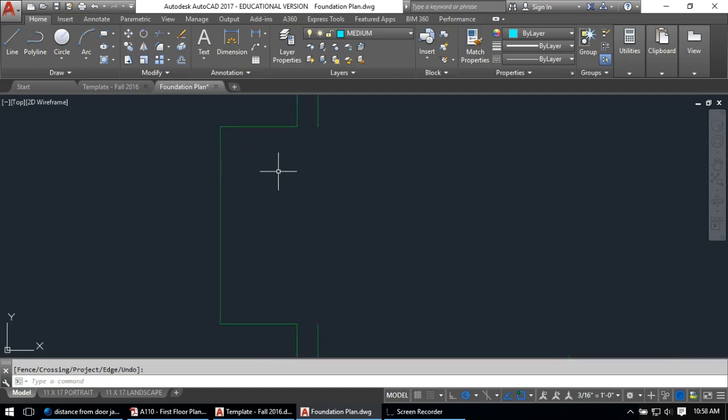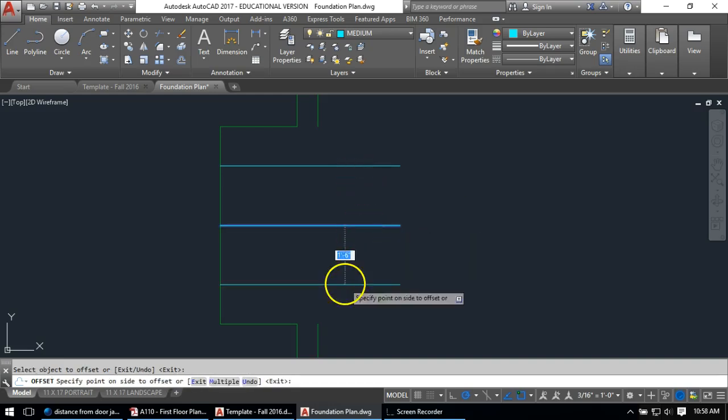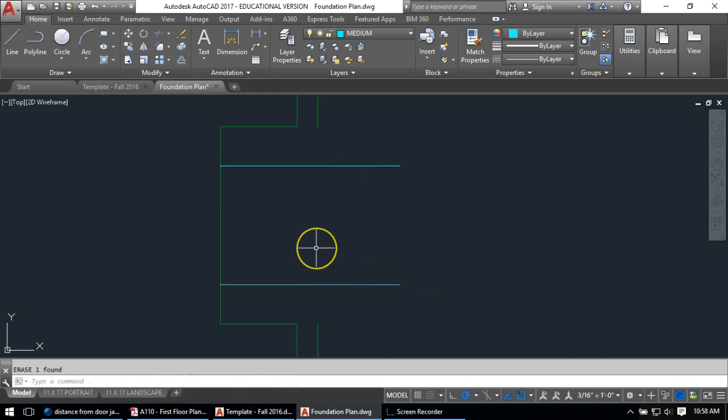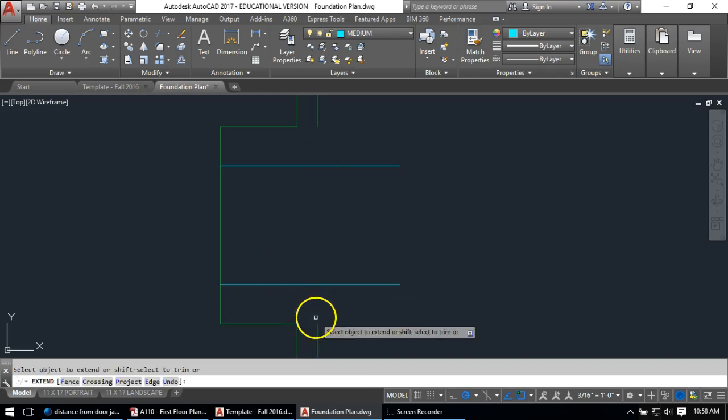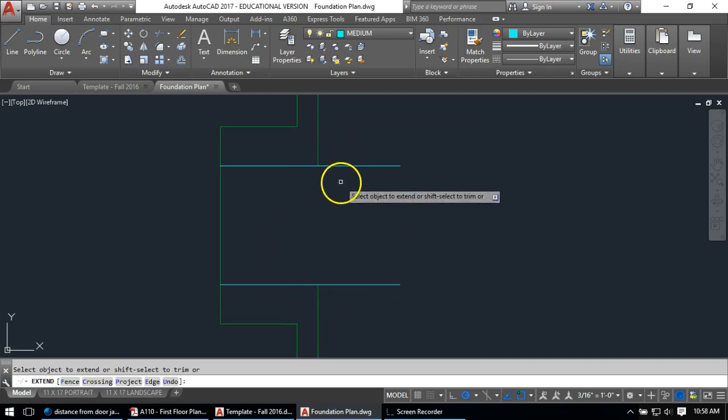We can see that we have an opening that's 3 feet wide at the front. So I'm going to start by drawing my center point down. I'm going to offset 1'6", which is half of 3 feet. There and there. And that is going to be my opening. Then we see that it angles back, and there's no specific angle.